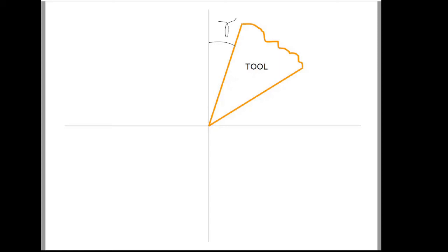It is assumed that you already know the magnitude of the cutting force Fc and the thrust force Ft. So initially we shall mark the cutting force Fc. The cutting force should be marked beginning from the tip of the tool or the origin. So the cutting force Fc is shown here. It is marked along the negative x-axis. The length of the cutting force Fc should be equal to the magnitude.